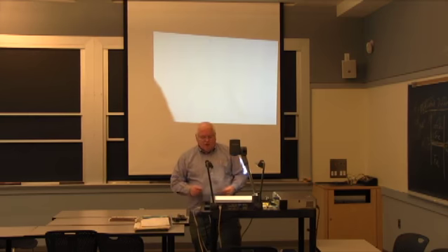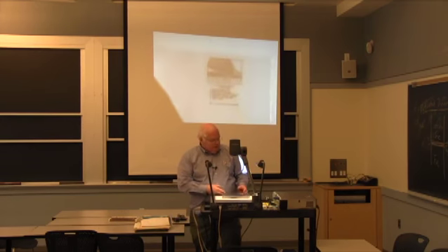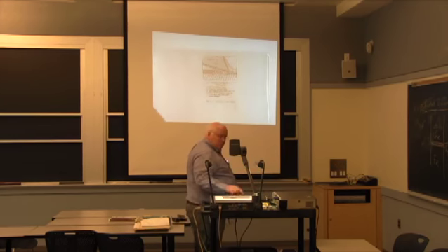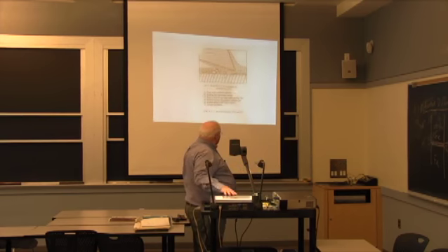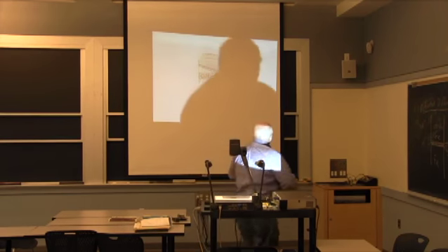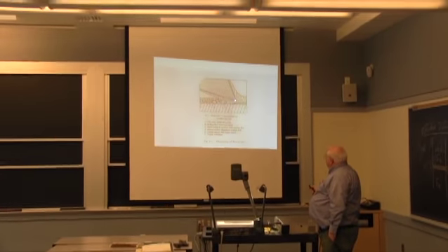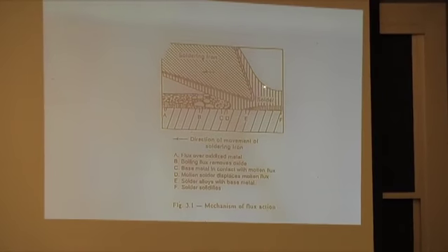Soldering has been around for years. Brazing came a little bit later, and people gave it a different name. And there are other problems with some of these things, but this comes out of an old soldering manual and shows the complexity of a solder joint. You got, in this case, a soldering iron, which has this intermetallic compound of iron tin, if you're talking about lead tin solder.